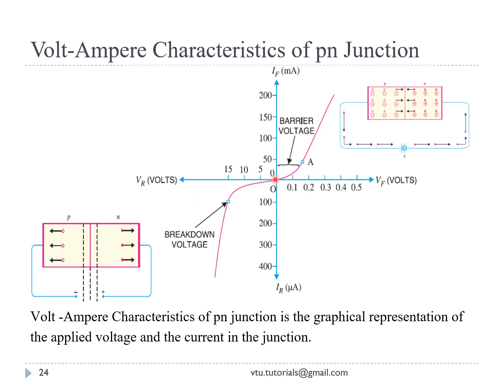by the curve over here, from O to this point. This current is due to the minority charge carriers. This minority current, or little current, is due to a few free electrons present in the p-type material and few holes in the n-type material.